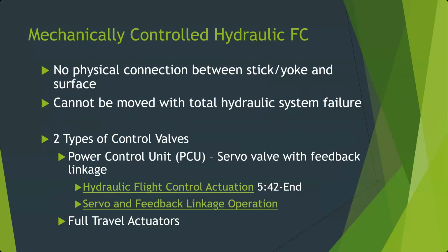And so here, going from small aircraft to large, we've severed that physical connection between the person controlling the aircraft and the flight control itself. All it's doing, like on this actuator I have here, this was a rudder actuator, when I move the rudder pedals back and forth, my rudder pedals were connected right here to this little arm. And all that arm is doing is moving this valve right here, which is what causes the actuator to move back and forth.